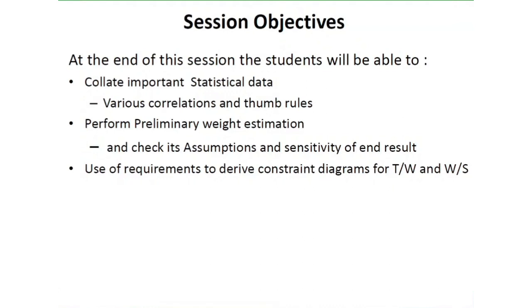So these are used as a way to get an idea whether what you're doing is within the ballpark or not. They are not to be used fully, but to check the numbers you get from different techniques. Are they all similar, and do they fall in the same bracket, so that you know you are realistic. Okay, and then you also have to perform preliminary weight estimation. This depends on looking at the payload the aircraft is supposed to carry, the fuel it is supposed to carry, and any other devices.